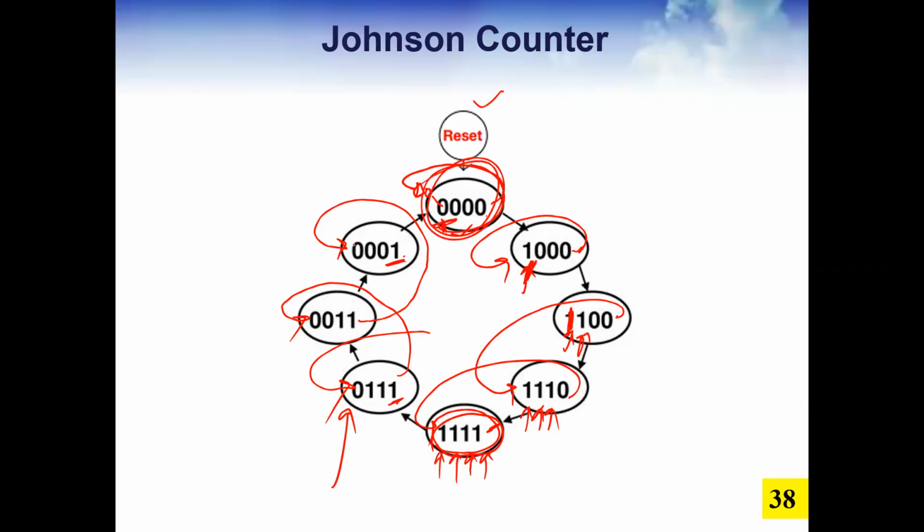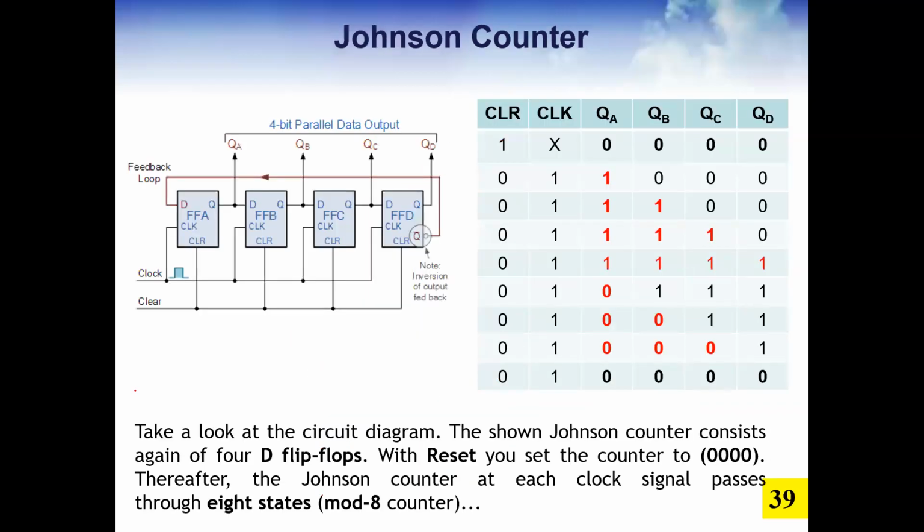So the design has just a minor change in terms of the ring counter and the Johnson counter, as you can see here. First of all, it is also performing shift and rotate operation. So we have four flip-flops. But instead of rotating the regular value, we need to rotate the complemented value. You know that each flip-flop has two outputs, one regular and another complement. So this is the complemented value. When the count is 0 0 0 0, the rightmost value is 0, so the complement value will be 1. Are you getting the point?